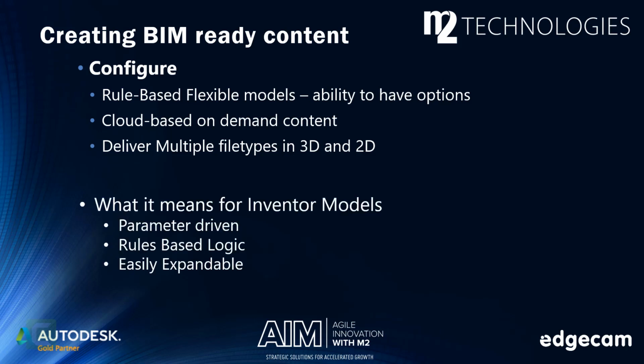What does it mean for Inventor? It means it's a parameter-driven model. We're going to use our dimensions and we're going to drive those models. It's rules-based logic. So, if it's this size, it uses these parts, or if it has 4 of these, it needs 3 of those. The nice part about that is it's expandable. We can keep adding to that. When we put it to Configurator 360, we also have the ability to control who can see what. So we can limit which customers have the option to see those parts and download information.